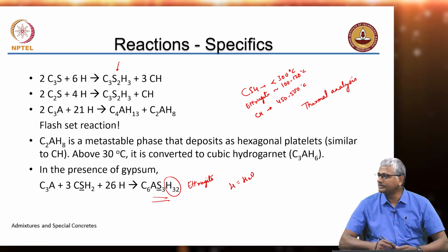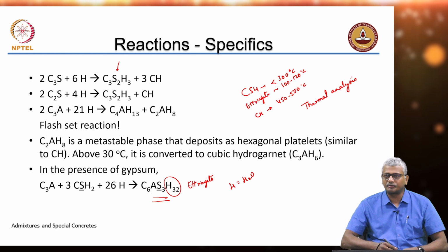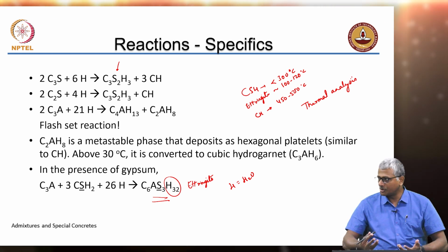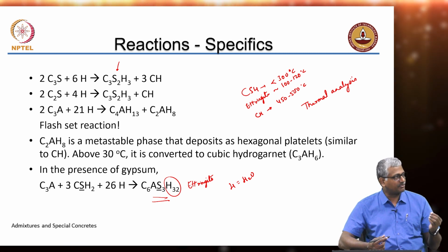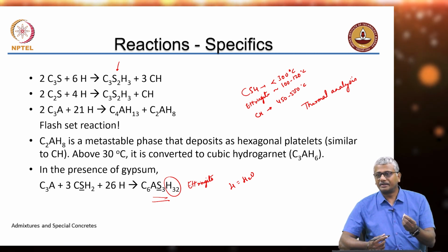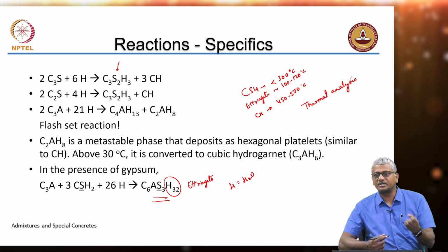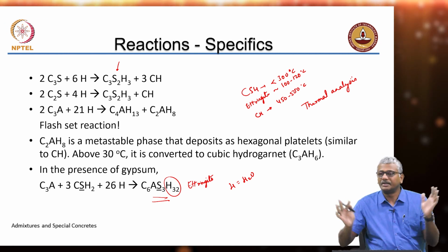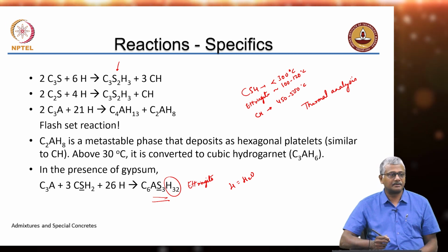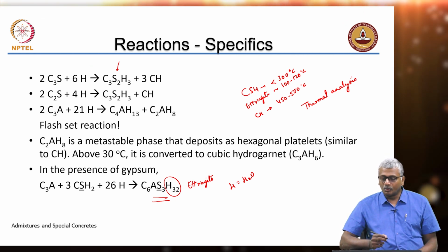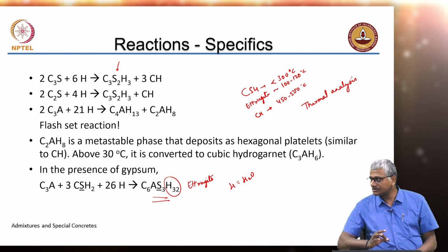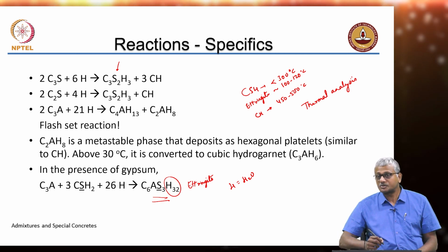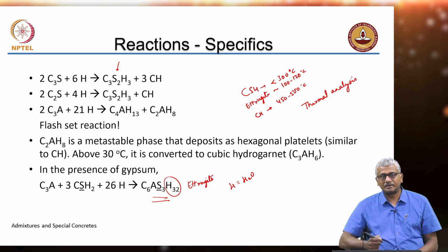Why does spalling happen? I mean, why should dehydration cause spalling? Moisture basically is trying to come out through the fine pores, right? It converts to steam. So, water expands when it converts to steam. It's trying to come out rapidly through the pores, and that causes the spalling. Okay. So, overall concrete deterioration will occur over a large temperature range, but spalling may start quite early.